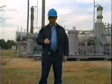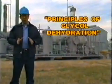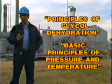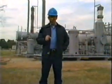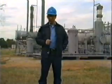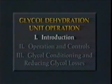Prior to viewing this program, you should have successfully completed the modules entitled Principles of Glycol Dehydration and Basic Principles of Pressure and Temperature. Now, if you haven't, please stop this tape and study these programs before proceeding. This is the first section of a three-section module on the operation of a glycol dehydration unit. In the first section, we'll look at liquid desiccants, the importance of dew point temperature and dew point depression, and process variables which affect glycol dehydration.